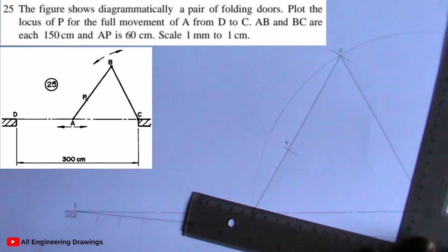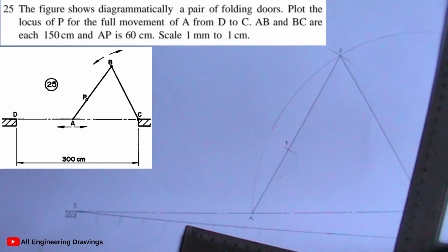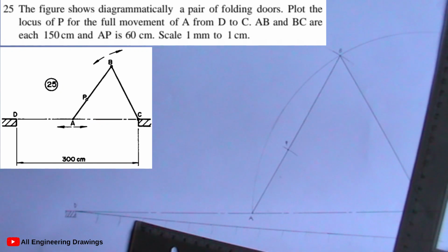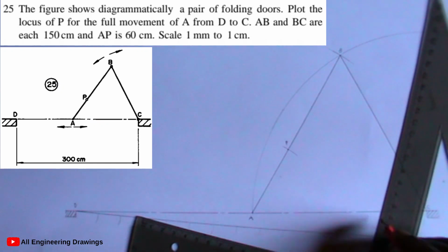Remember, your ruler should be touching your line DC. So you set it. So this is the principle of line division. So this is how line division is done. Then you slide to the next one, without moving your ruler. You keep sliding.